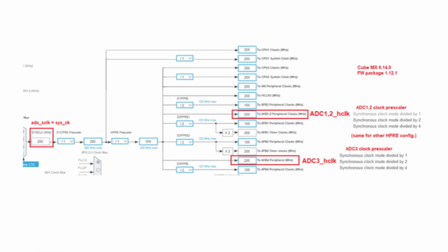And the clock prescaler, how does that fit in? The ADC needs its own clock to time its internal operations, like those steps in a SAR converter. This ADC clock is usually derived from the main microcontroller peripheral clock, like the APB2 clock on an STM32, by dividing it down using a clock prescaler. You might divide the main clock by 2, 4, 6, 8, etc. Faster clock, faster conversion.